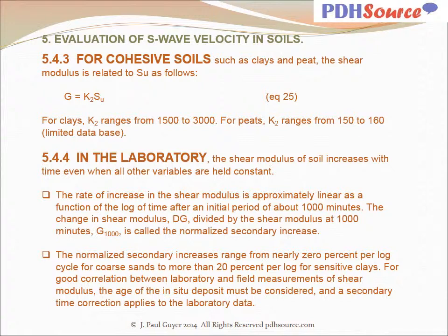For good correlation between laboratory and field measurements of shear modulus, the age of the in situ deposit must be considered, and a secondary time correction applies to the laboratory data.